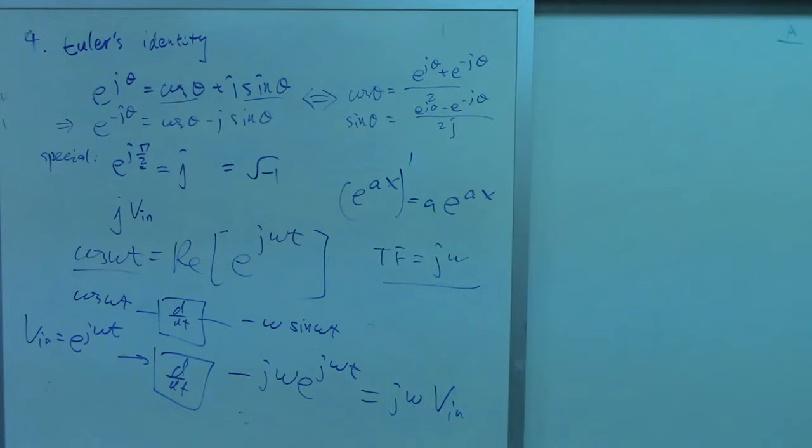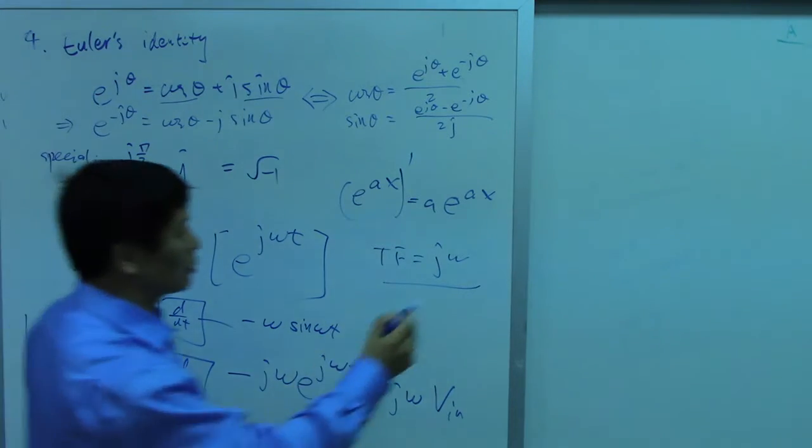Basically, we have 4 types of transfer functions. Because the input can be voltage or current, and the output can be voltage or current. So we can use output voltage over input voltage. That is what we know before as the gain of an amplifier. We can use the output current over the input current. That's called current gain. We can use the output voltage divided by the input current. The unit is ohm. Still a transfer function. Or we can use the output current divided by the input voltage. So the system is like this.